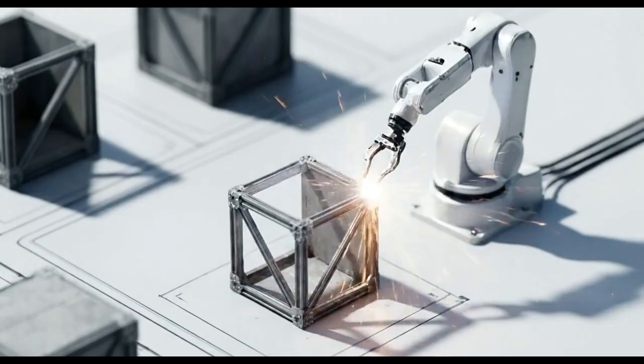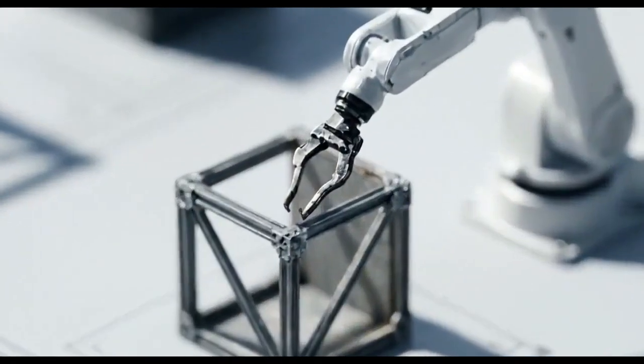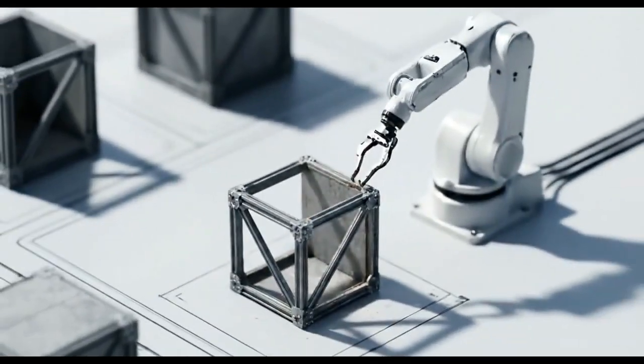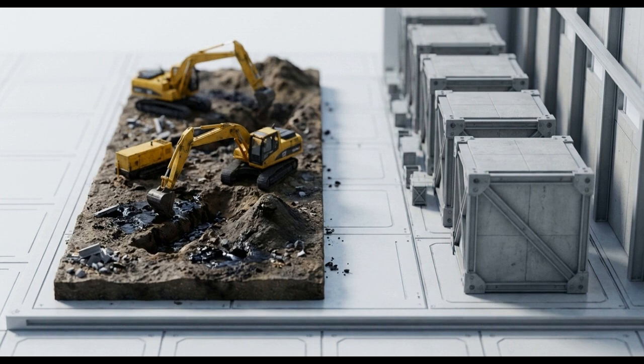This process allows massive elements, like complete volumetric modular rooms and precast concrete panels, to be manufactured in controlled factory environments. Shifting labor off-site reduces material waste and cuts on-site labor requirements by up to 70%, bypassing local skill shortages. Off-site production enables the structural modules to be manufactured simultaneously with the contaminated brownfield remediation, significantly compressing the project duration.